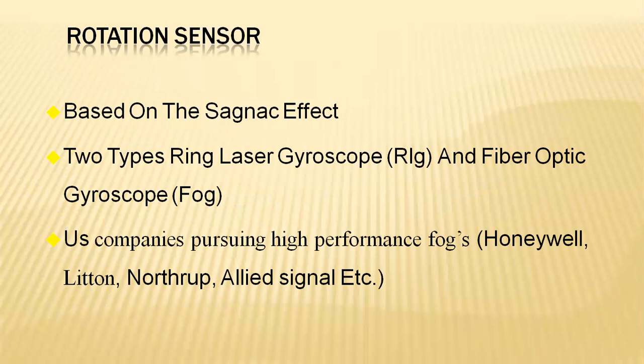With the concept of the rotation sensor, which works on the basis of the Sagnac effect, here we have two types of rotational sensors, which operate on the basis of the ring laser gyroscope and the fiber optic gyroscope.